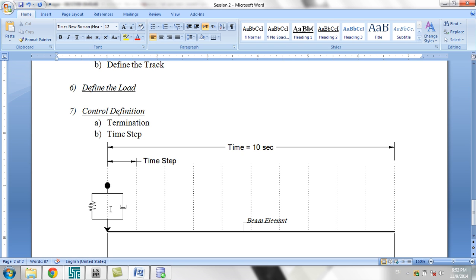If it finds any instability problems, for example, that to solve this system during this time step, the velocity of this mass needs to be 1e31, 32, or whatever, then it finds an instability problem for this model. Then it will stop the execution of the model. So how to solve this problem? What we have to do is to reduce the time step. Instead of having a very big time step, we have to reduce it.